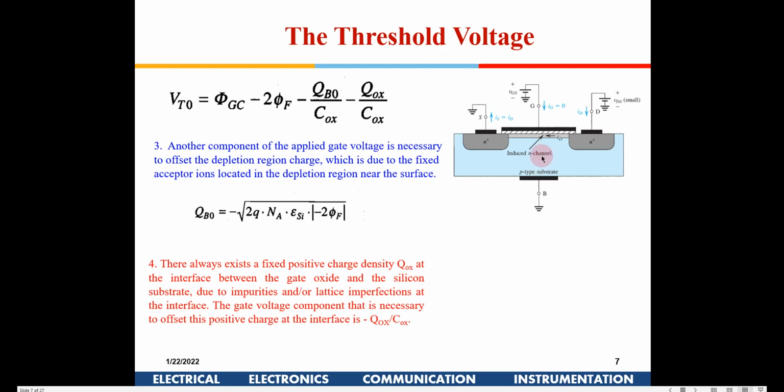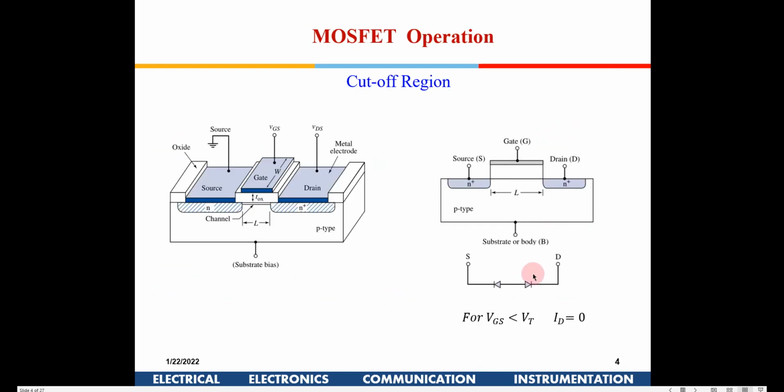If you reduce the doping density of the P region, then when the gate voltage is not there, this diode which is formed here, as we said earlier, will become weak and there will be leakage currents. So that is the trade-off, right? If you increase the doping density, then during the cutoff region there will be lesser leakage currents.